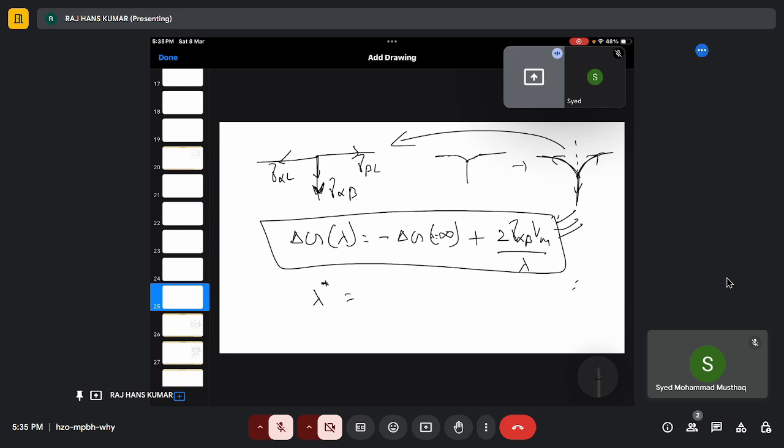How do you define that? Easy, just like we have done before. Equate it to 0. You will have 2 gamma alpha beta times Vm times equilibrium temperature, effective temperature here, or change in enthalpy times delta T naught. This is the undercooling. Right, now what does that mean? If we increase the undercooling, the interlaminar spacing will decrease. Now if I decrease the undercooling,